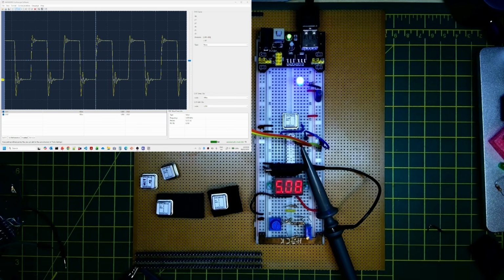So that was getting to a situation where it might actually start to cause some damage to chips being connected to it. But in reality, the frequencies of address and data buses are probably going to be more around the sort of 4 megahertz signals and lower, just because of the way the bus cycles work. Even with a 16 megahertz clock, we're likely to need multiple clock cycles to actually do memory reads and memory writes, and so the frequency on the bus and address rails is likely to be less than certainly 8 megahertz.